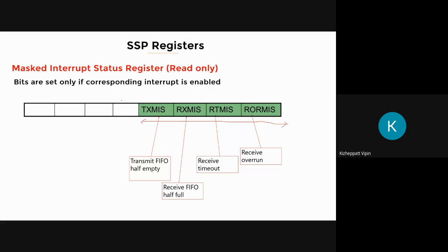In the datasheet also, you will see the meaning of mask is opposite of the meaning of the mask that we have been using till now. As per ARM, this SSP module also NXP bought from ARM. ARM makes a lot of soft IPs. So there they will say only if you mask you will get interrupt. So don't get confused. The meaning of mask is opposite in this scenario. That's why. Don't get confused, I just wanted to say.